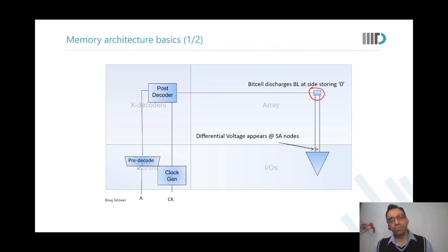Why don't we have 2 bit lines in those ROMs and DRAMs? We've done layouts now. If I have to route 2 metals versus 1 metal, what is denser? One metal is denser, so I won't need space. Yeah. So we want to keep it dense.